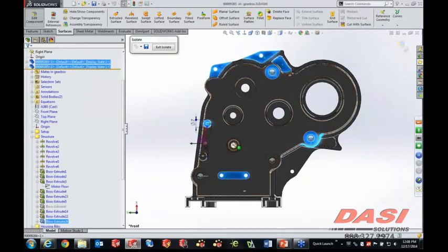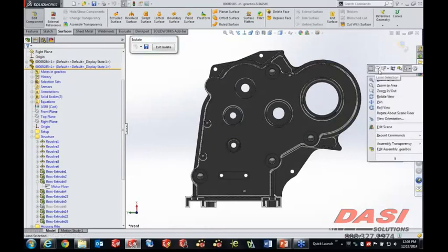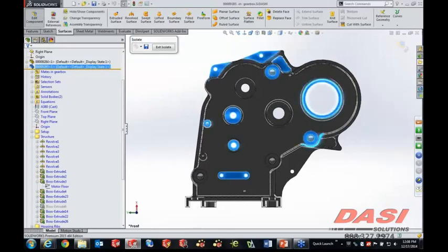These could be edges, sketch entities, a lot of different things. And there are times at which the pick gets so meticulous and maybe even a mispick takes place. You click and you deselect all that stuff that you took the time to pick. Well, now there's a right-click option that shows up on this quick toolbar right in the middle here, simply called Previous Selection. By clicking that button, it will activate all of the entities you previously had selected before you clicked